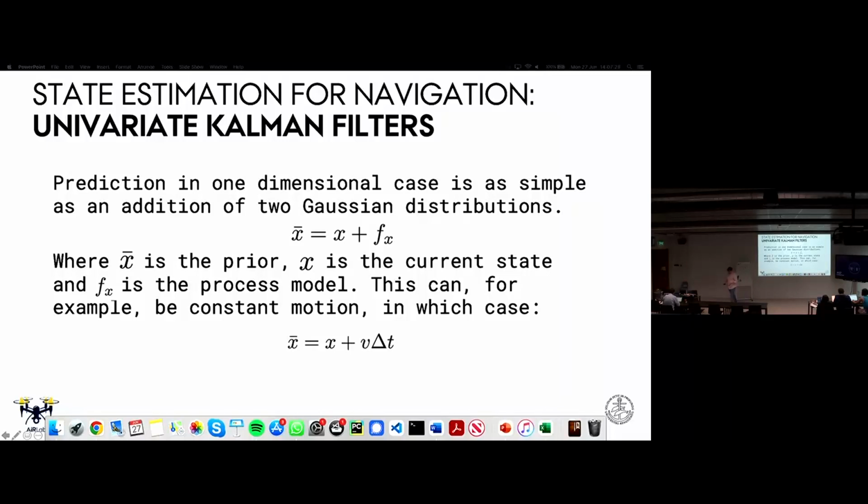And this is mainly because we can consider that we have some certain state in our localization context, and we can say this is a location on a unimodal, one-dimensional line. So if you imagine you only have a one-dimensional world and you can only move in one direction, then we can define a state just by a position, or relative position, from the origin. And then from then on, you can see how that position changes given some form of a process. So the process model, this variable here, actually defines how the state is going to change given some model.